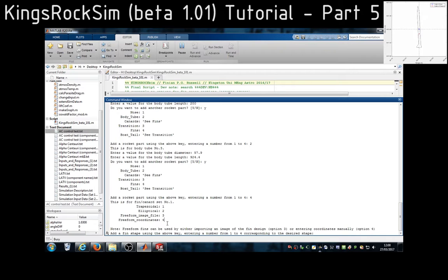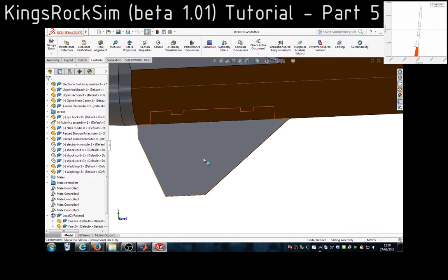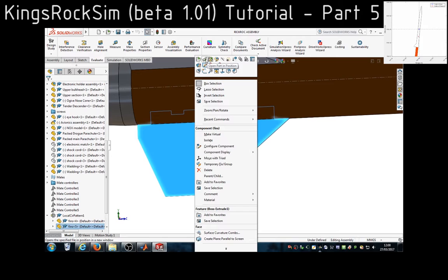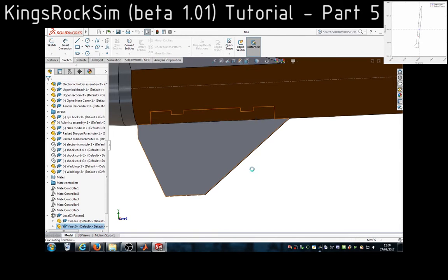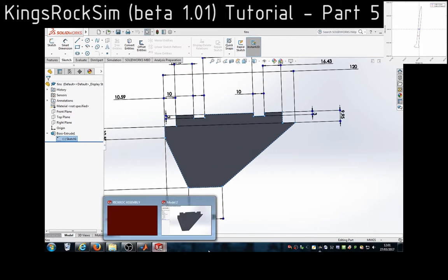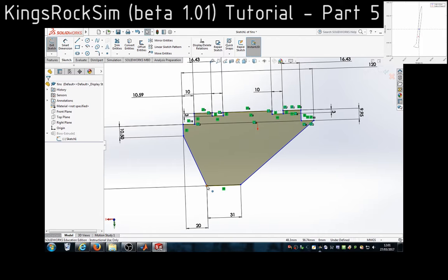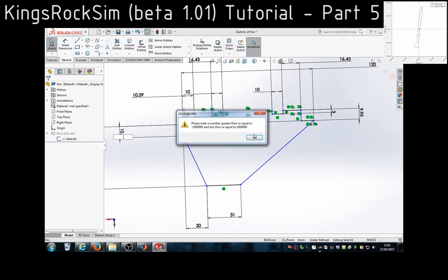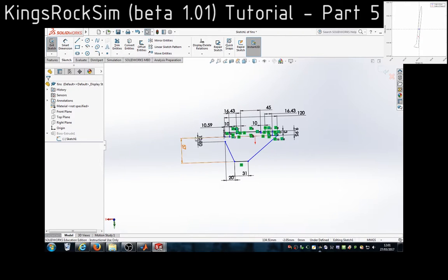Or you can enter coordinates for vertices on the fins, along with one base dimension, which will be the root length, and it will then scale the dimensions of the other side to match the base dimension and the coordinates you entered. In this case, it might just be easier for us, for this video, if we instead remove that short side and make the fins trapezoidal and save freeform fin designs for another video. So we'll do that by entering the sketch in SolidWorks and deleting that one short side and matching up the end of the long slanted side with the base of the fin.